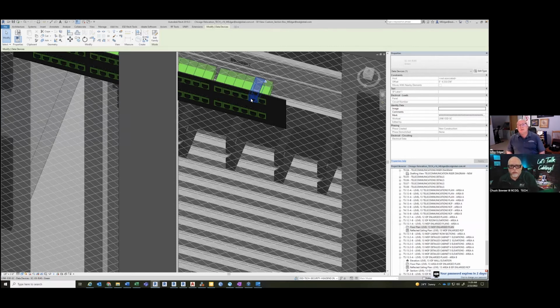And circling back around, one of the things I want to touch base on is you mentioned the weights. That's one of the things that I think is a weak area when it comes to estimators and designing stuff, because we don't really look at the weight of the racks and the panels and the cable and all that stuff, because the floors have a structural integrity that you don't want to exceed. And there's even some stuff in the TDMM that says that.